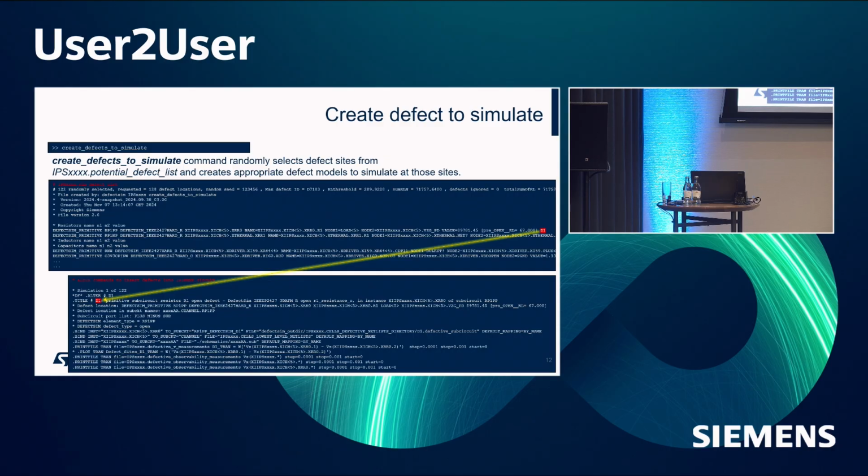It is not, of course, possible to inject an enormous number of defects, but the more relevant ones will be chosen by the tool. And each defect, which is named D1, D2, and Dn, will then be in an .alter command inside the netlist, replacing the non-defective device.